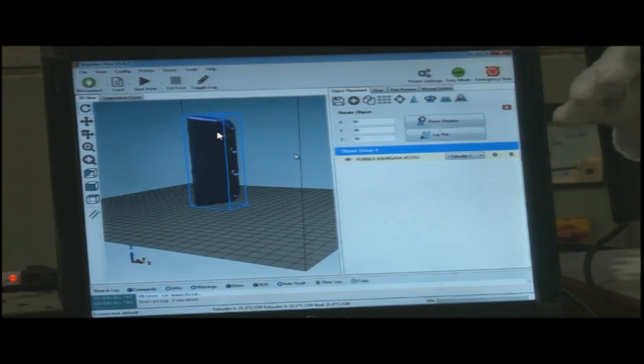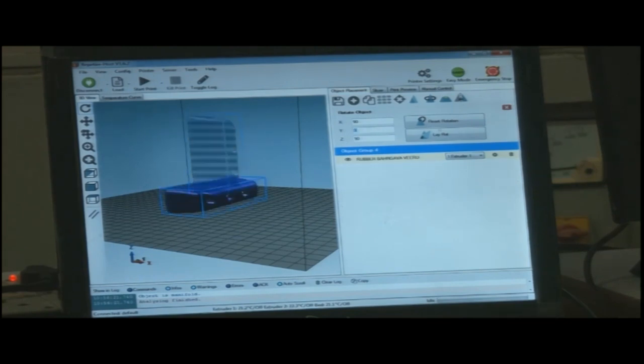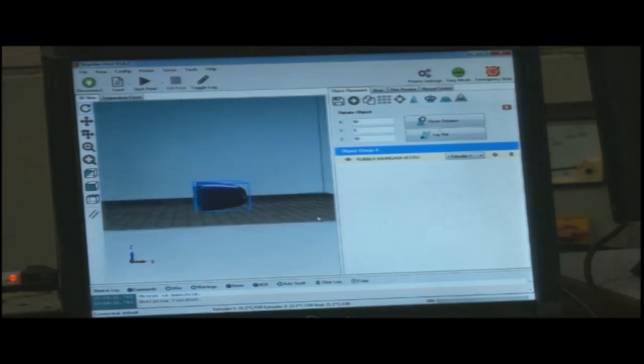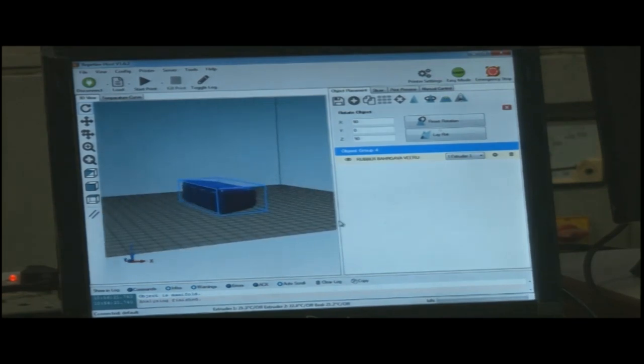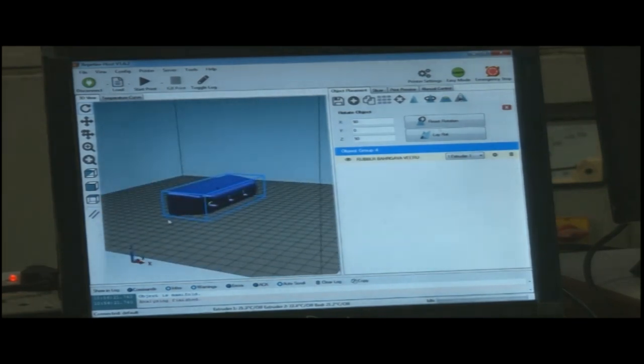Total time means total cost of the product would also increase, because in the product cost function the machining time is one of the factors. So this is not a very good position to manufacture. So we can opt to select the flat position and orient the job in the proper place and position.